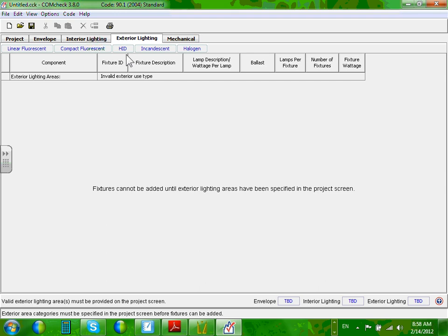By the way, the whole software here, you know what they're looking at? They're looking at the watt per square foot. You want to maintain your watt per square foot below a certain value to pass the energy code. By maintaining watt per square foot below a certain value, you are conserving the use of energy for our future generation. Do I sound like a politician here? Cool. Does everybody know what the outcome is? Dumping all your lights here, you get one value, a watt per square foot. Based on this value, you pass the energy code, this type of energy code, or you don't. If you don't, you're going to go back and redesign. Thumbs up. We know what we're doing, right?